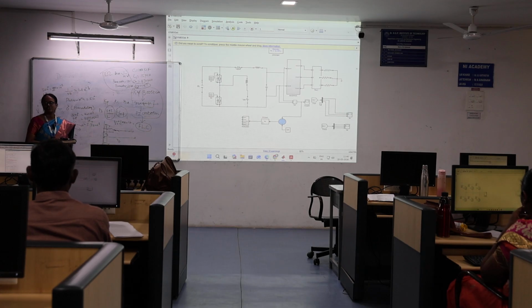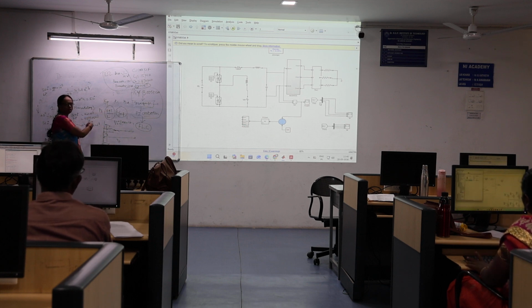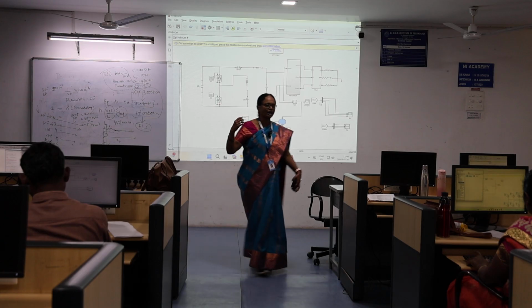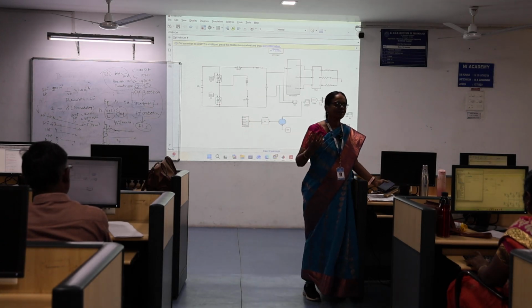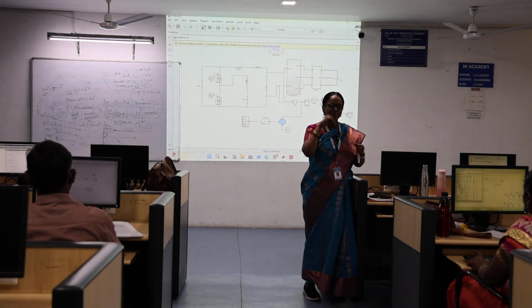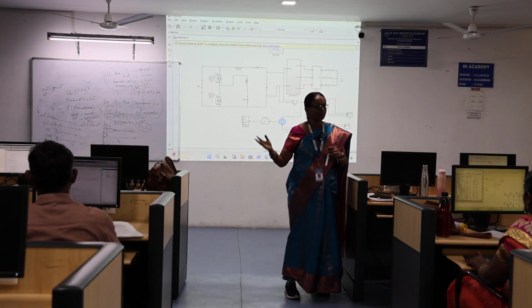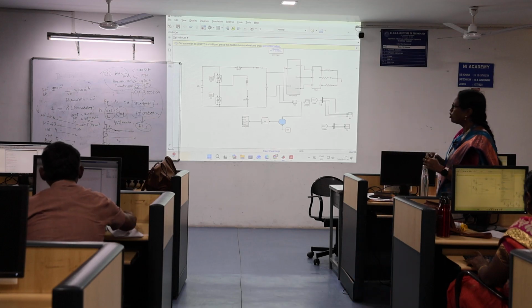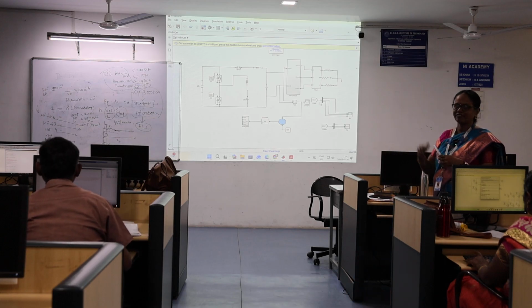Open loop condition, how we ensure the values, we will get now. In the closed loop condition, find the output waveform, and from the waveform find my Kp value and Ki value using these formulas, and then try to settle it there. Normally when you go with a converter, which is the best controller? There are so many optimization techniques, but the PI controller, and apart from the PI controller we may say the fuzzy logic controller. These two are the very best controllers, and using these two controllers we may design and reduce the values also.